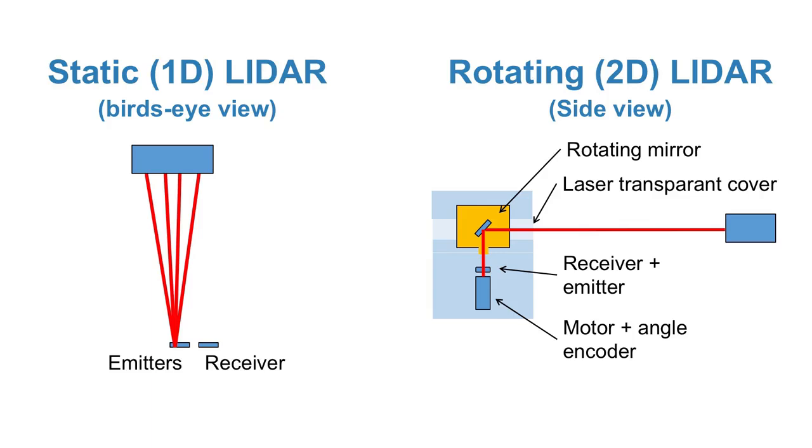Typically, the laser transmits and acquires measurements several thousand times a second. An angular encoder is measuring the angle of rotation of each individual range measurement. The combination of range and angle provides a position relative to the vehicle, which can be expressed in Cartesian XY coordinates if needed. The resolution of range depends on the laser measurement unit, while the angular resolution is determined by how fast the mirror rotates in relation to the frequency of the laser pulse, as well as the angular resolution and precision of the angular sensor.